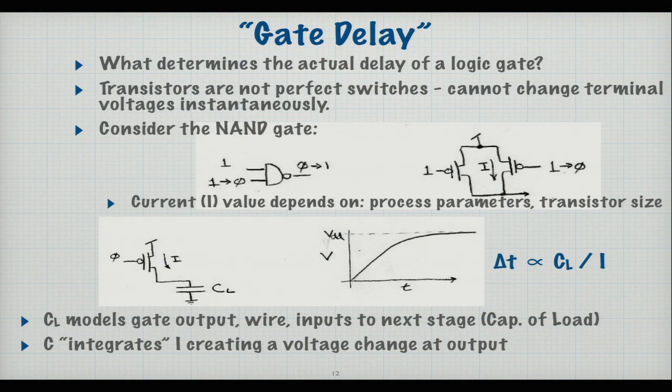It's a double-edged sword, though. If you make this transistor wider, then you increase the capacitance that the gate has, and so the stage before it will get slowed down. We'll get into more of that later, but it's kind of a tricky business.